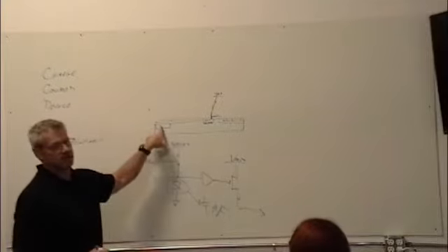What these ones tell me is my charge transfer efficiency, how well I'm shifting through. What these ones tell me is dark noise. Tell me about dark noise, because remember we talked about thermally generated stuff. So if I've done some amount of integration time, I can look at this and say, oh, I'm getting this many electrons per second noise. And that's a statistical process, but I can kind of lay it across the whole thing and say, I expected to be this many electrons of noise.